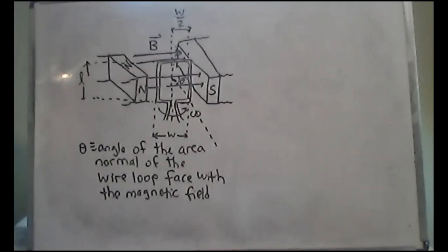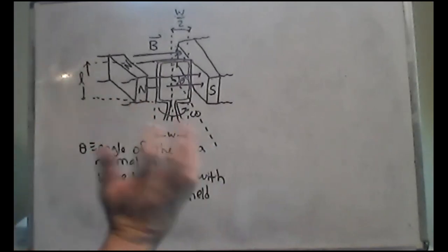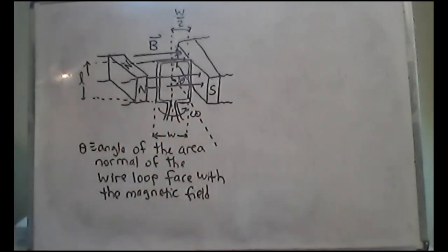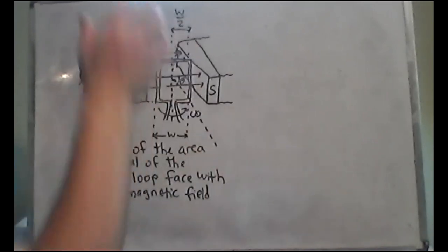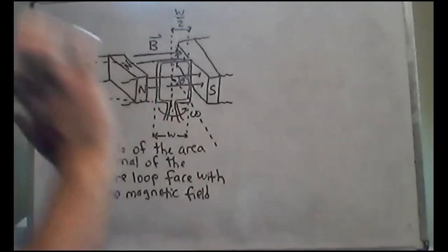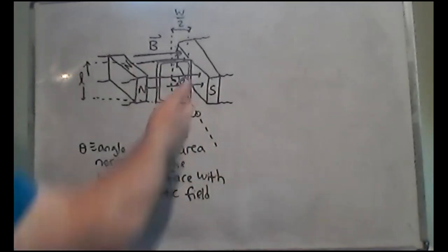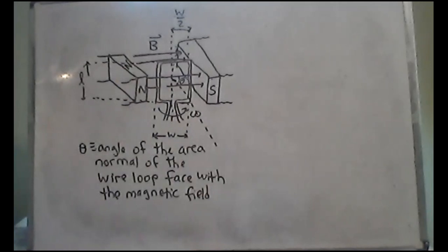Now, what's going to happen here is that you're going to use mechanical work. You're driving the shaft this time. Last time you used electrical magnetic work to actually drive the shaft. Now you're going to use mechanical work to drive the shaft and create electricity. Last time you used electricity to give you mechanical energy. Now the driver is going to be maybe a gasoline engine that's going to drive the shaft and give you electrical energy. So it's the exact opposite.